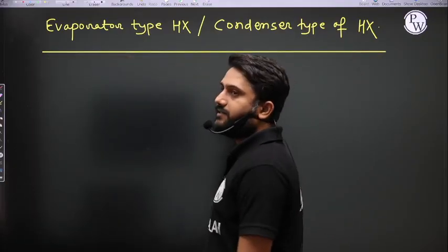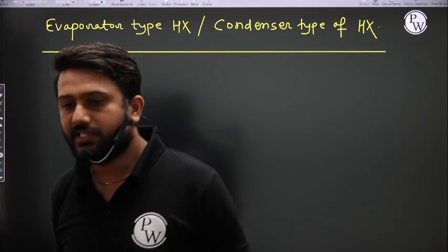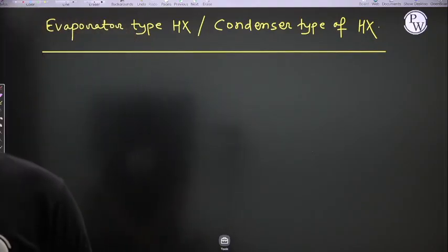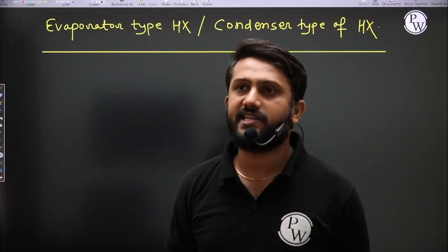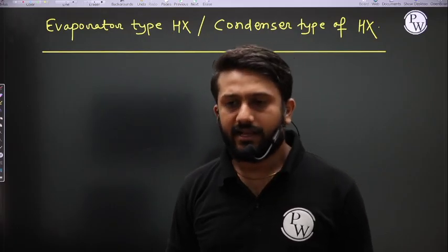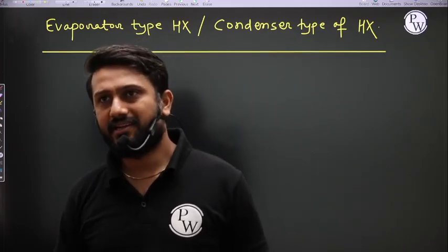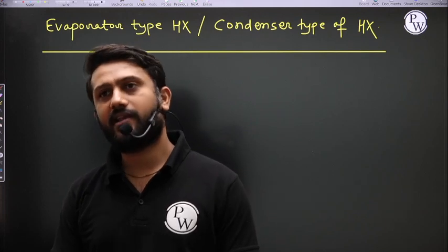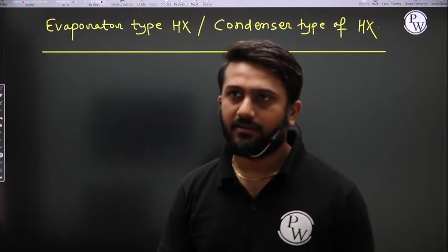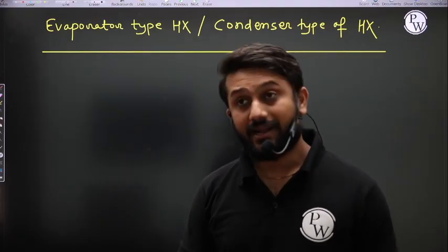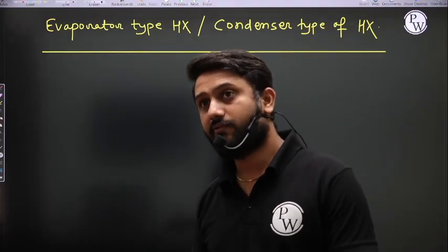if there is a heat exchanger in which one liquid undergoes phase change, then it is immaterial whether the flow is parallel flow or counter flow. Right? Because if flow is parallel, then you are getting the same LMTD as if you assume the flow is counter.